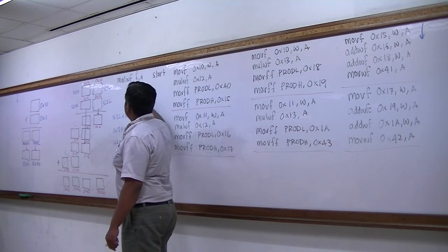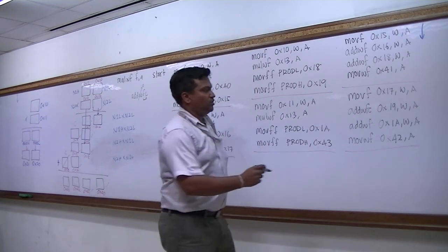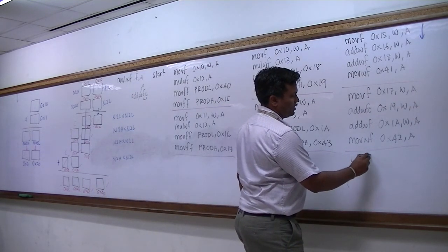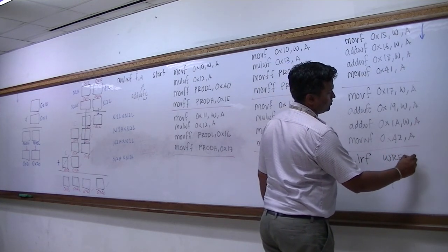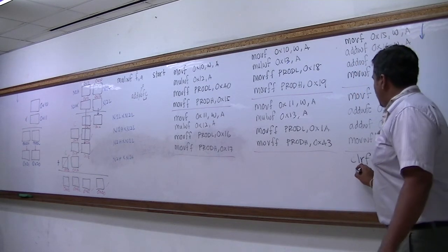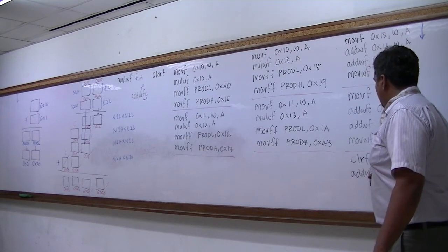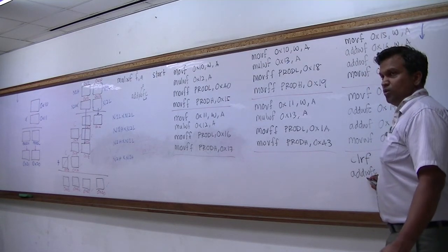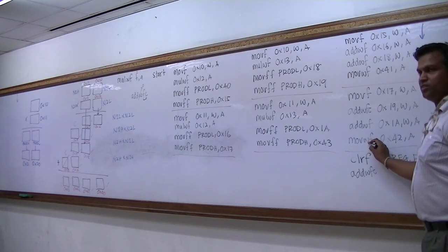So what we should do? We should make this 0. So what you can do is you can clear F working register. So I'm clearing F working register. And then I'm going to add the content of working register. Content of working register is 0. Why I need to make it 0? Take note that the previously working register got some value.